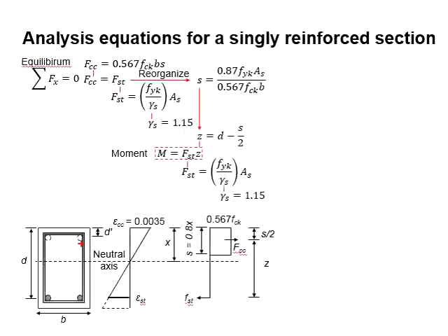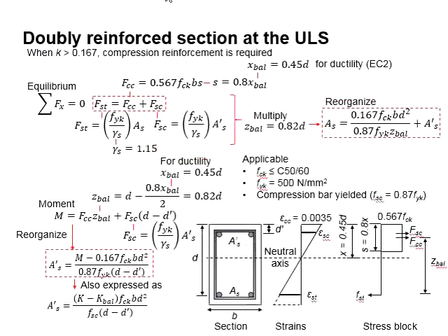We also mentioned that the singly reinforced sections will only require the tension reinforcement bar. The compression reinforcement bar is not required. However, for a doubly reinforced section, the compression reinforcement bar is required. The area of the compressive reinforcement bar is represented by the symbol A's.